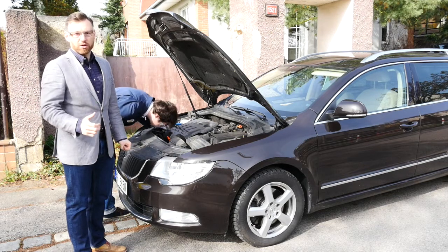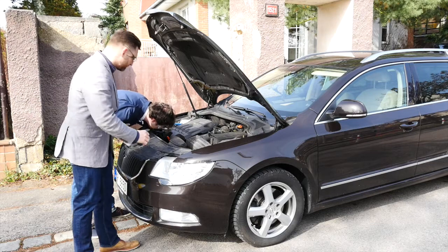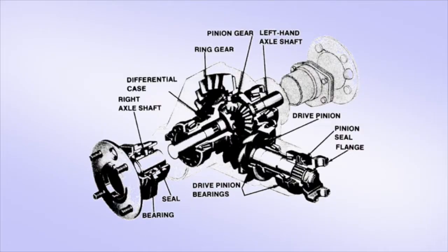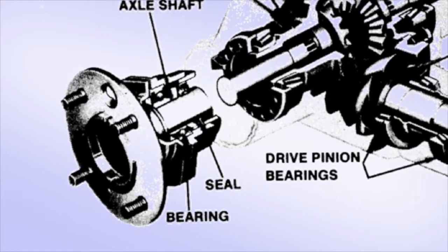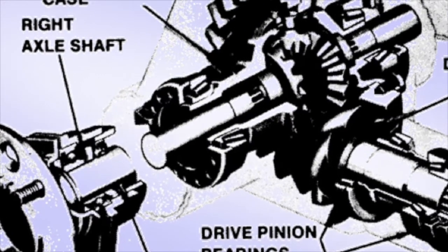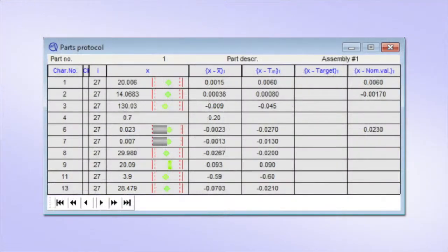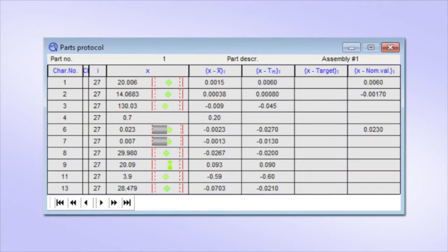The automotive differential was found to be interfering with the gearbox housing. This was a single event, but it raised questions how likely it is to repeat. Through the inspection of the components, it was found that the critical dimensions in the used parts conform to the specification, and moreover, that the process capability was also within acceptable limits.